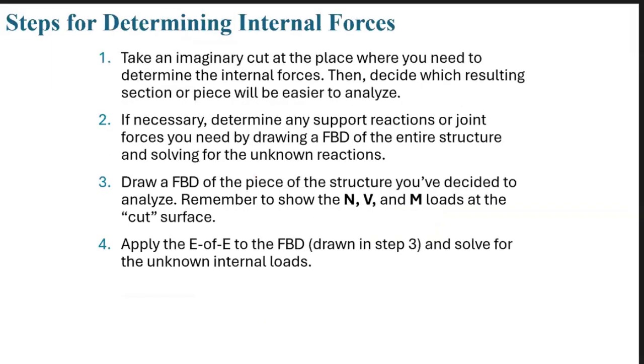Okay, let's summarize the steps for finding the shear forces and bending moments at a specific point, or for drawing the shear force and bending moment diagrams. The first step: take an imaginary cut where you need to find internal forces. Second, find the support reactions using a free body diagram of the entire beam. It depends: if it is two-dimensional, we write 3 equations of equilibrium: summation of Fx = 0, summation of Fy = 0, and summation